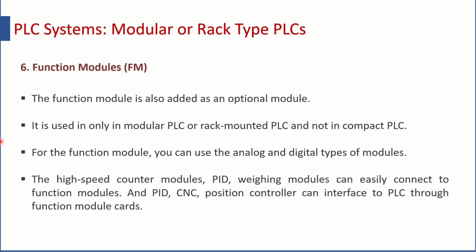And such specialized modules include high-speed counter module, PID module, weighing module, thermocouple module. And if you need further operations like PID, CNC, specific position controller interface, then such types of module cards have to be mounted in the PLCs. Now you see that there are new generation PLCs which accommodate such types of modules already built in onto the PLC, even if they are compact in nature. Okay, they can be added with further modules, but with the basic system, definitely whenever I will show you one figure.